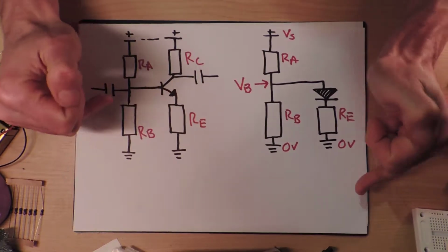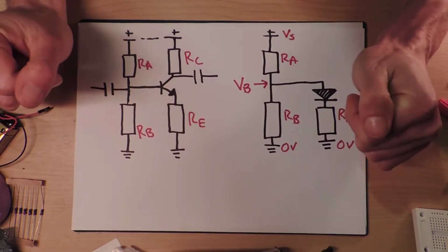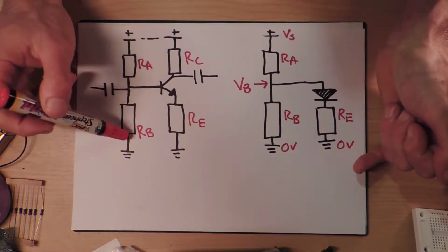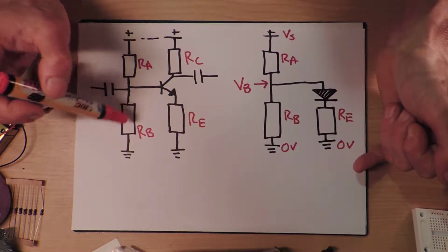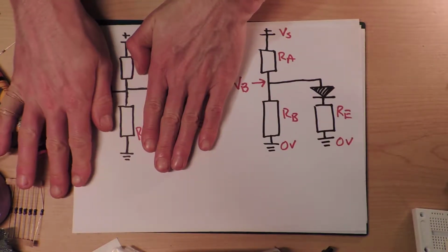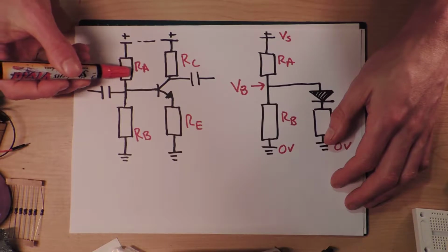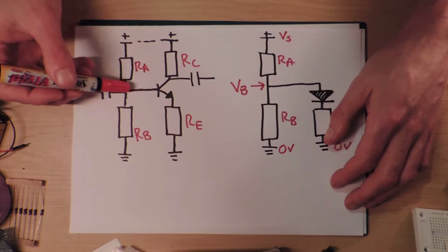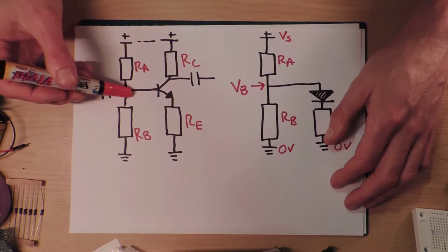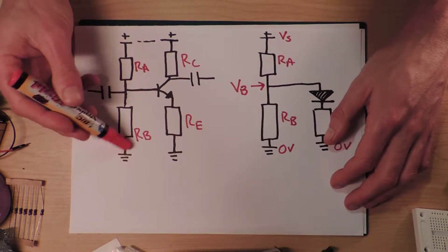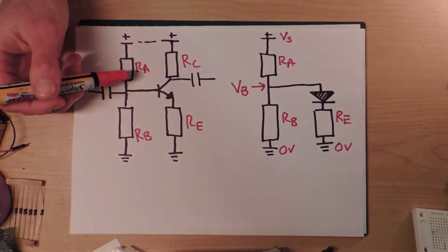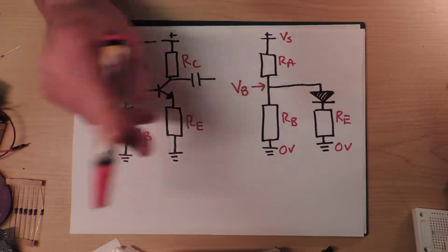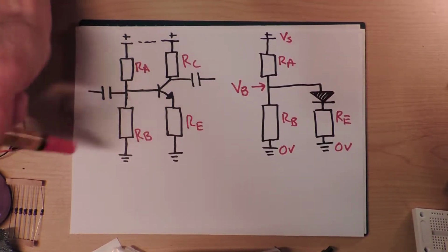But what I'm kind of interested in, so when I've been reading these things in books and stuff, they usually say that this is biasing it at the voltage that you would think you would get if this was just a voltage divider circuit. By that I mean if this was, say, 1,000 ohms and that was 1,000 ohms, then this would be biased to halfway between the supply voltage and ground. But this feels really strange to me, and I actually think I misunderstood what they mean.